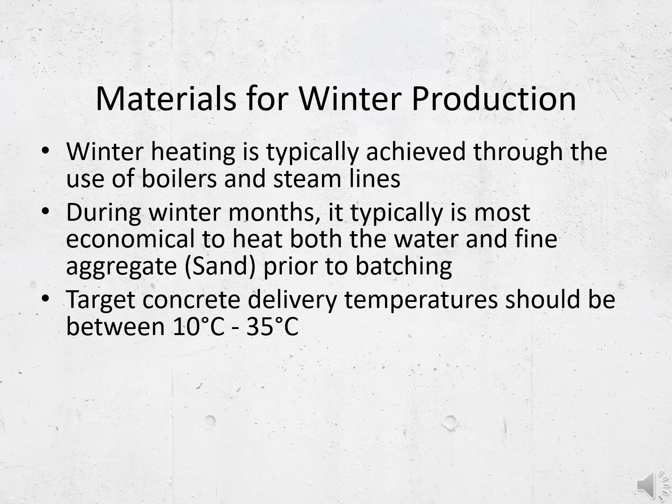Look for boilers and steam lines in sand pile bins. Ask to see evidence of boiler functioning during current or most recent winter operations. Ask to see batch tickets with ambient and concrete temperatures recorded as evidence of dispatch of concrete within 10 to 35 degrees Celsius.